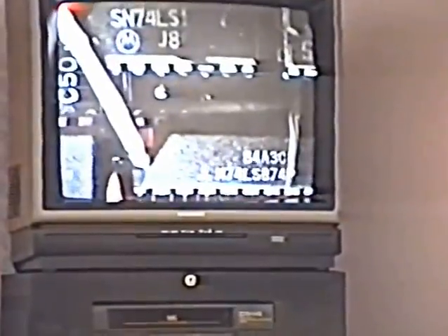Things you'll see, like there's the notch right here. That's pin number 1. Now this dot here, it's right in the center. That's just where they extrude the plastic into the mold. This is the notch that we're looking for here. See if I can find one with a dot on it. Here, see the dot in the corner there? Anyway, you get the idea. So that's pin number 1, and the pins are numbered counterclockwise around the integrated circuit.